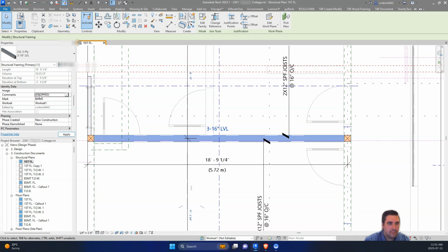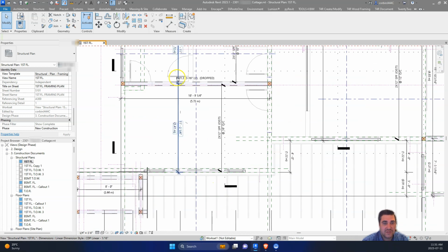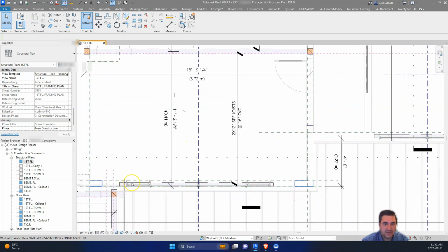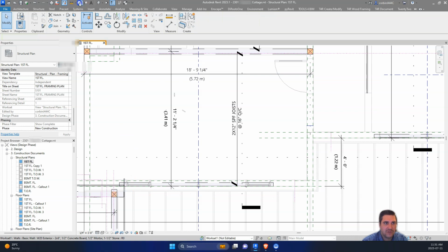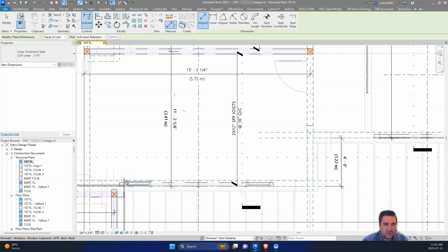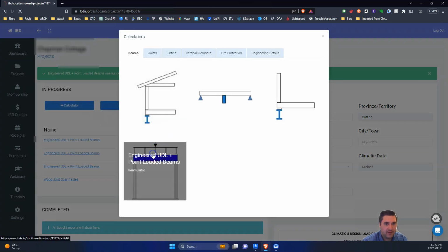Last thing I want to just show is sizing a lintel. So we have this lintel right here. This lintel is supporting these windows right here. Again, just to make things easier, I'll add a dimension from the side of the window to the side of the window. So that's a 12-foot opening. And then we have 11'2" as our span. So let's go back up to here. We have calculator, UDL, and I mean, we could actually try not using a UDL. We probably actually could do this one without a UDL.